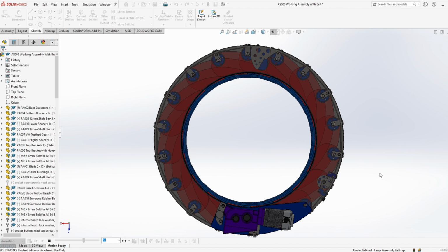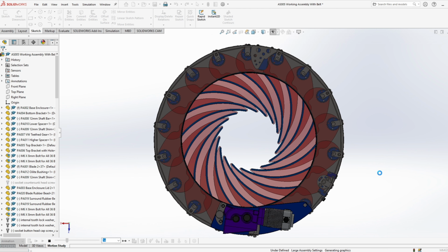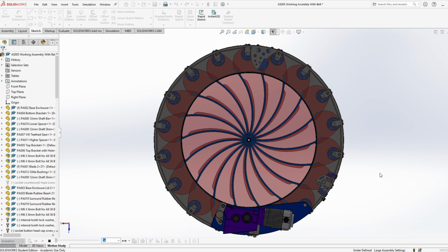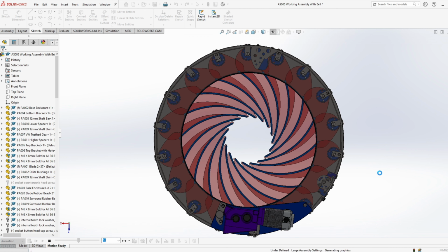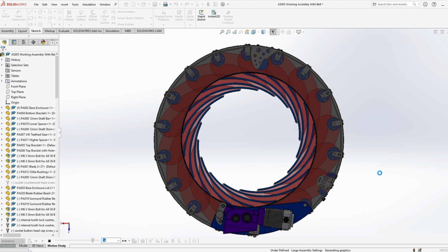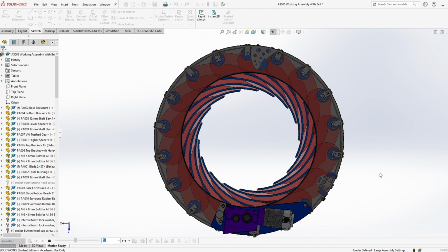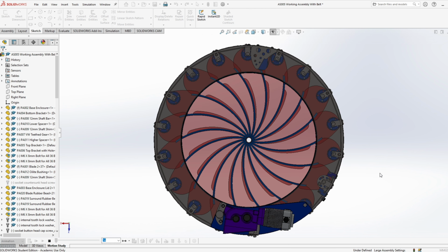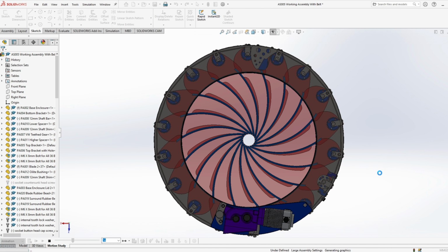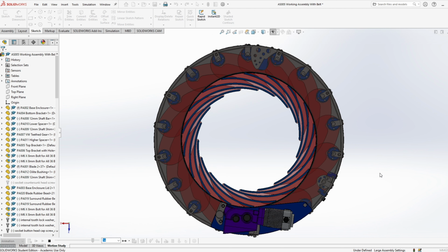Okay, so the first fact being the blades were reduced from 2mm to 0.9mm thickness to relieve stresses during Prototype 2 to allow more flexibility within the system. Also, the blades were altered to remove the square corner at the opposite side of the hinge point, the gear side, to reduce unnecessary contact causing drag or binding issues, where everything tended to be more rigid in this area.